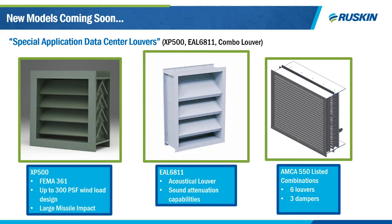For tornado regions, such as the central United States, if you needed something even more robust than the Miami-Dade model I mentioned earlier, the XP 500 meets FEMA 361 design and construction for community shelters. It also meets ICC 500 for large missile impacts up to 300 PSF wind loading. This louver also has a UL listing, so it's still maintaining the strong performance and has a free area of 46%.